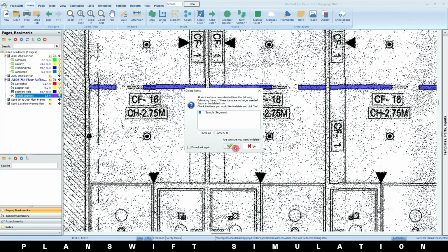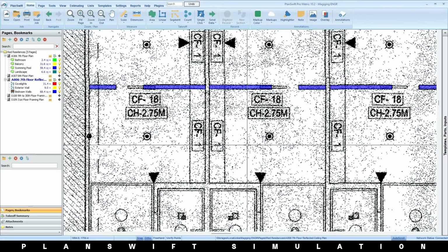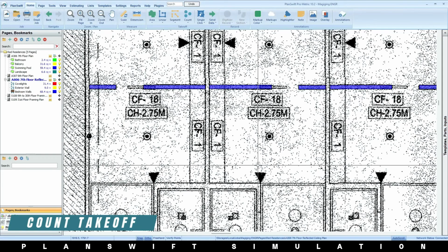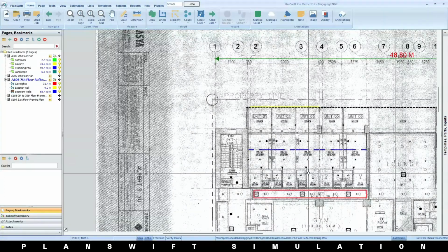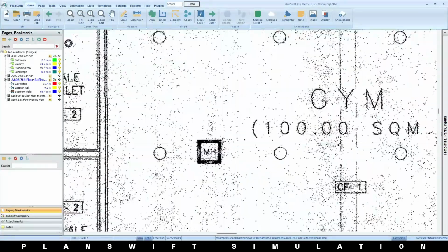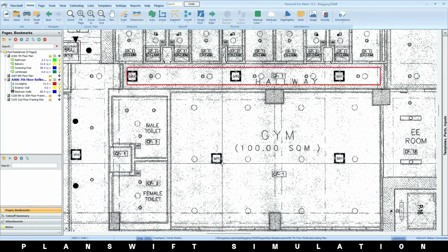Now, Ms. Peralta will demonstrate the last takeoff tool. Finally, the last takeoff tool, the count tool. From the word itself, the count tool simply counts items in your plan such as doors, vents, manholes, trees, and many others. Let's count the manholes in this plan.